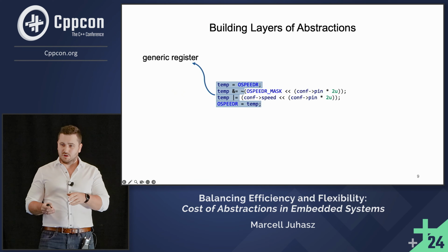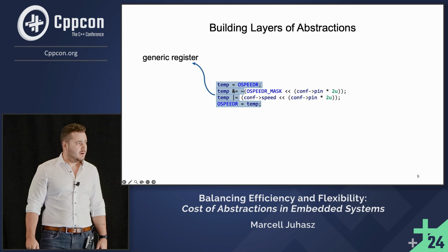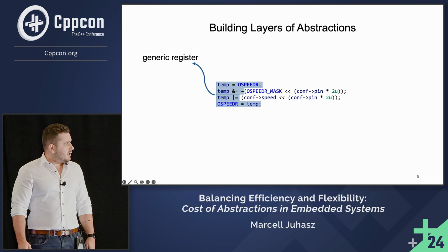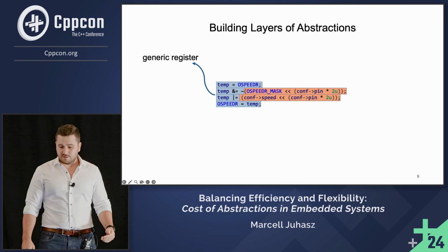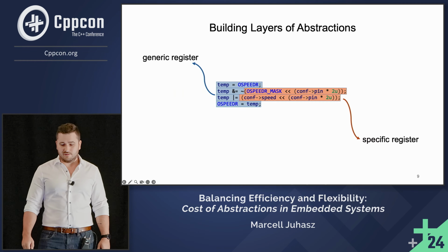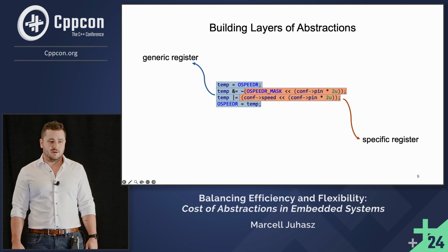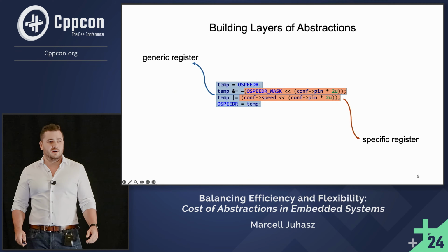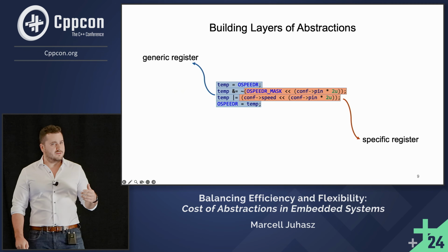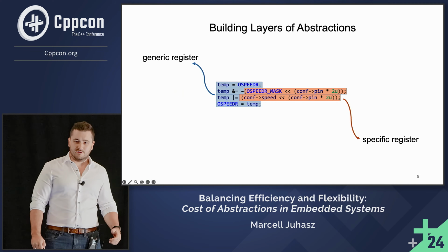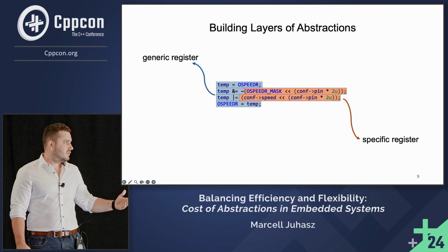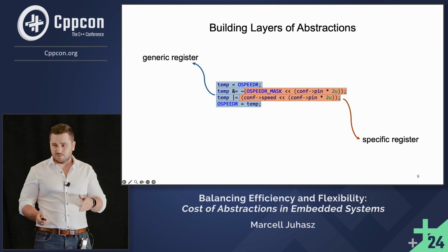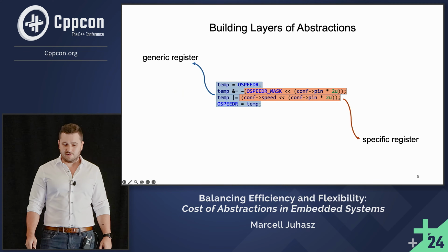It simply handles the bit manipulation of every register, independent of its type. The second part of the register operation is the register-specific part. This is the one that handles the bit mask calculation for the register operations. This part must know the meaning of every bit in the register, and it also must or should provide meaningful member functions to interact with the underlying register.